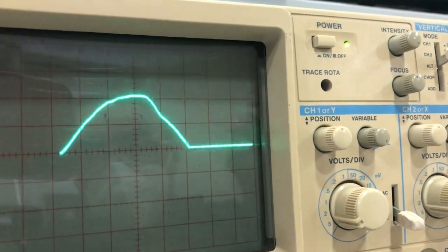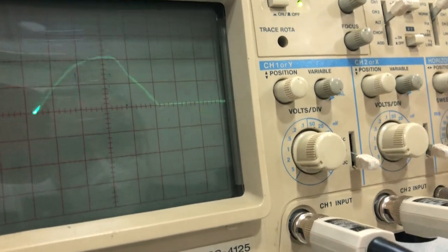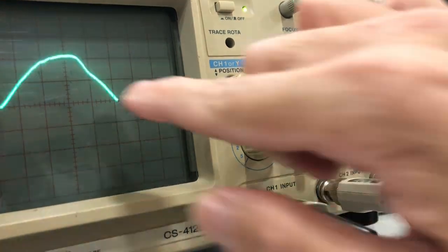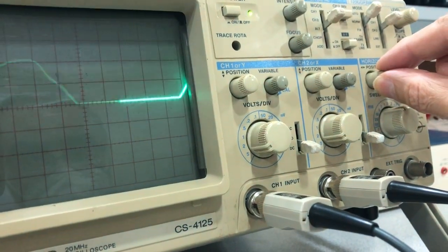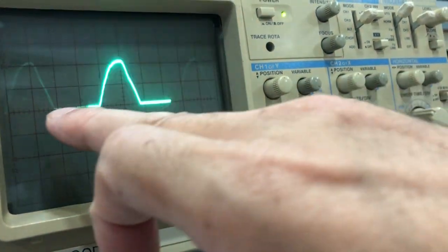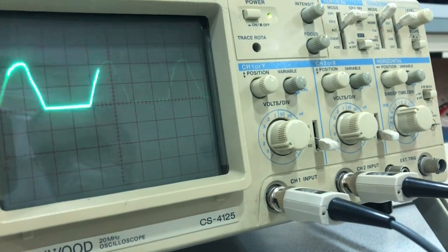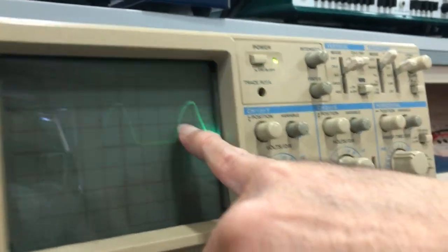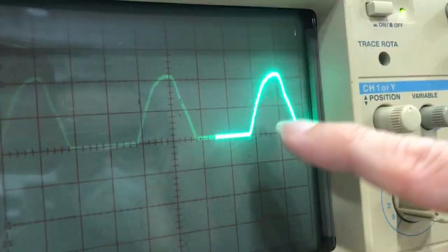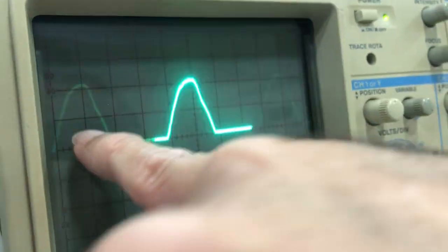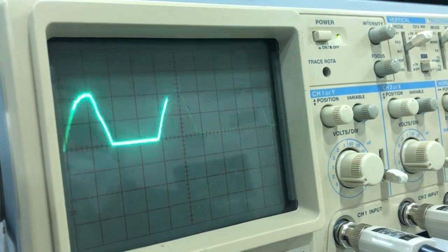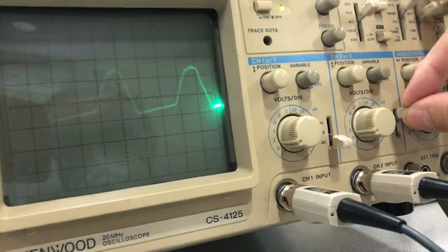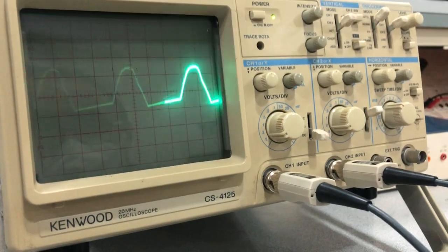Before we do the measurement across the diode precisely, let's talk about what happens if I move this to AC. Now this signal, we call it a pulsating positive signal, because the diode passed only the upper half of the sinusoid. Its average is approximately here, meaning the average is the line where the upper areas match in size the lower areas below the line. When I move this to AC coupling, the oscilloscope puts a capacitor in series with the input signal.